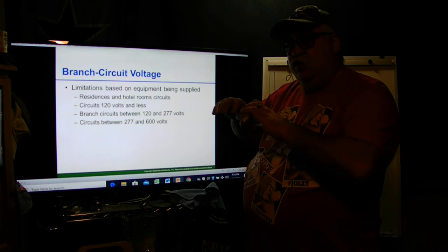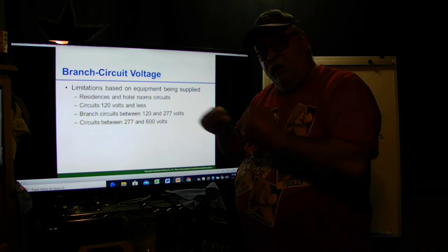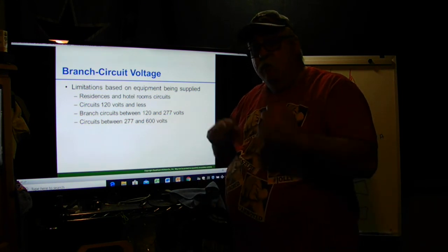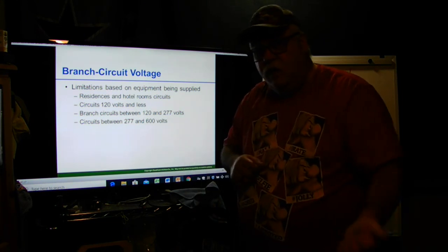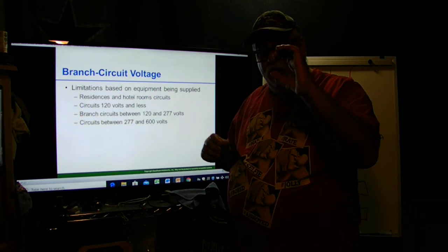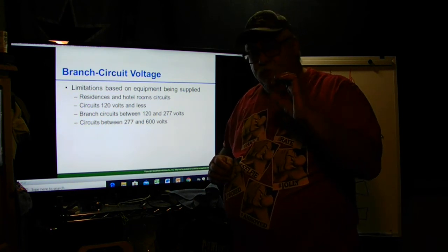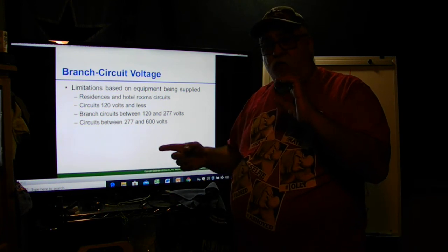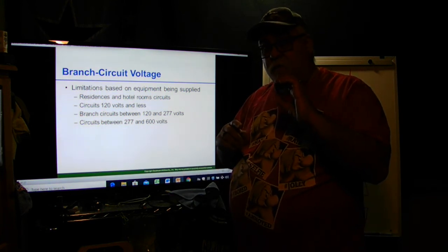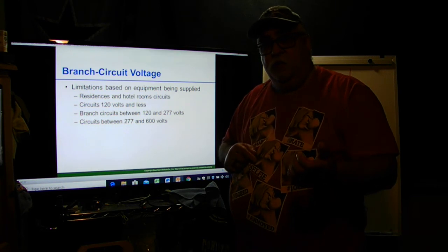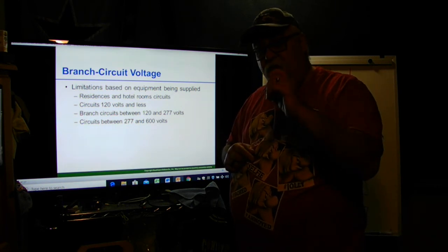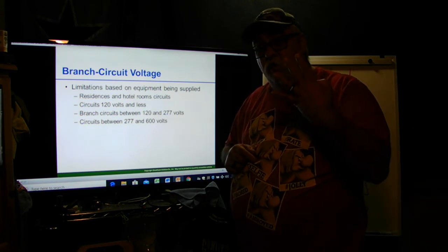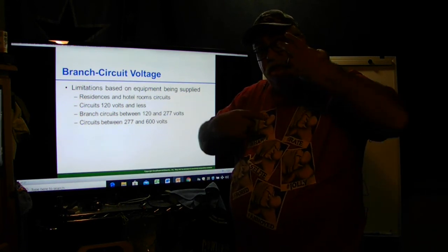But your capacities, your infrastructure, what you use, your wire, your conduits, you're using less at a higher voltage because you can put more things on the circuit. Because if I have a 450 watt light bulb, and I power it at 480 volts, I got less than an amp, but I still get that same 450 watt light bulb at 120. Now that thing's going to have almost 4 amps. Okay, so that's the difference.